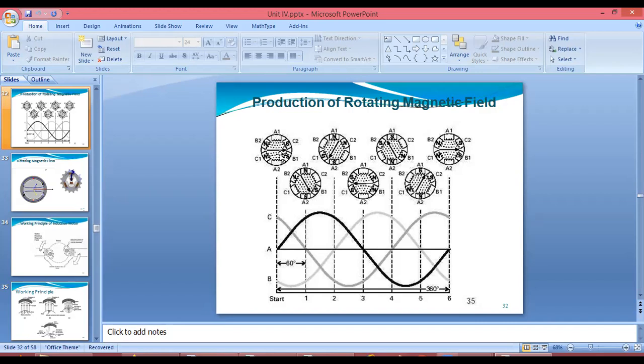Radius is nothing but the perpendicular distance when your magnetic field rotates. So mathematically, torque equals F into R into sin theta. Or you can take mechanical power PM equal to EB into IA, back EMF into armature current, or mechanical power in the form of torque and angular velocity, tau into omega.